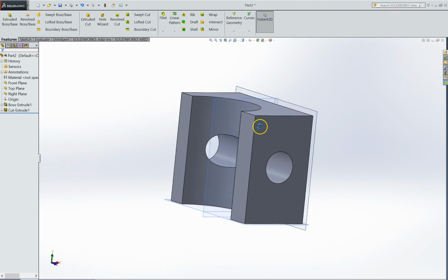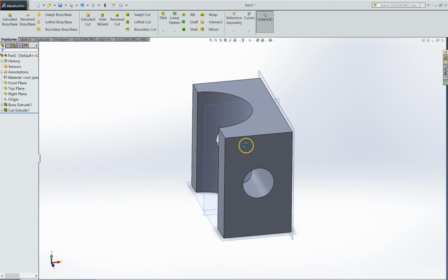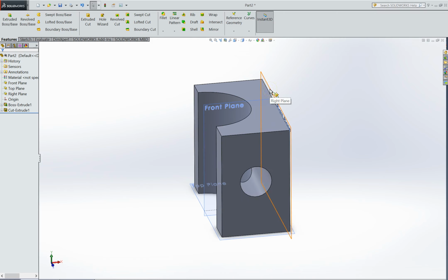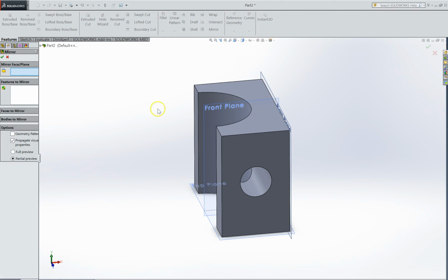I want to mirror it, so I can have it on the side. I've got this plane here, and I can mirror it about this plane. So imagine that's my symmetry plane. I've modelled half of my part, and I want to mirror it about here. So, click on Mirror, top. The first thing it asks you for is what is that mirror plane. So in which case I'm going to click that datum plane in the middle.